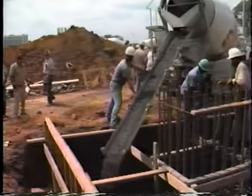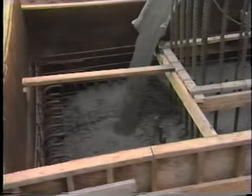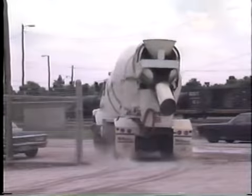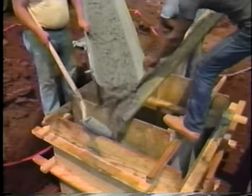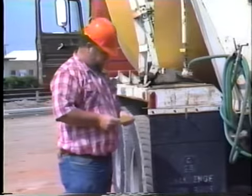In practice, however, the concrete ordered for the job may not be the concrete that's actually placed. At critical points during production, transport, or handling on site, the concrete's quality may be jeopardized. Batcher mixer slips are not always a guarantee that you have the right concrete in the truck.